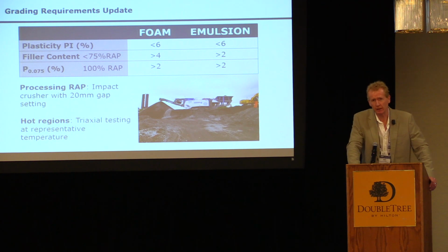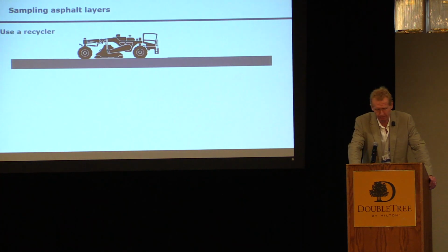When one's using CCPR, I think you call it, the in-plant type of recycling, depending on how you are acquiring your RAP, and the grading that you've provided with, as well as the variability of the material, it can be really worthwhile to pre-process it through, for example, an impact crusher. It does certainly provide a consistent product, and that leads to more consistent performance.